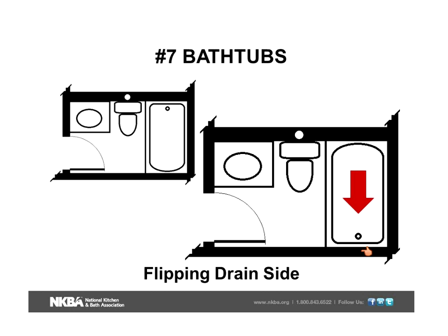Now, all I have to do is change the location early on in that plan. And whether it's a concrete slab or whatever it is, as long as the plumbing has not been roughed in, we can put it on the other wall. I don't have to have a vent stack this large on the opposite wall. A 1.5 inch vent stack would be fine for this. All it has to do is move air to the outside of the house.